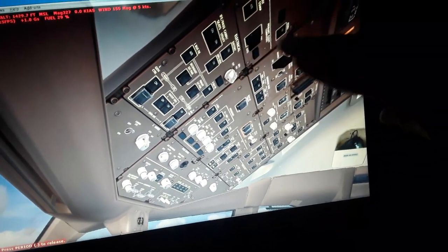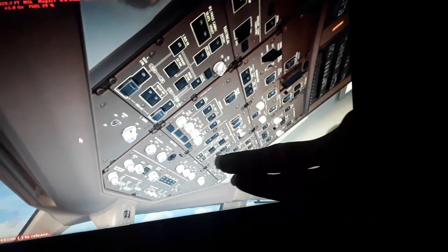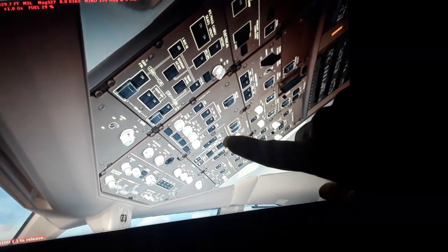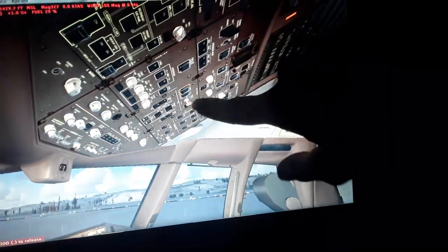I'm going to show you the air data and inertial reference unit, the primary flight control computers, the hydraulic system, the left and the right engine driven pumps, the ram air turbine, the passenger oxygen, the engine, the cargo fire, the electronic engine control for the engines, the fuel jettison, the fuel system, the left and right wing, and the center tank fuel system over here with the fuel booster pumps and the crossfeed valve. You can balance the fuel between the left and right wing using this crossfeed valve.